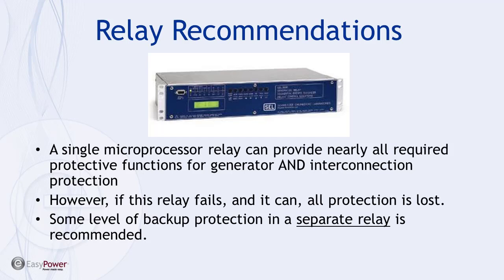However, if this relay should happen to fail, and they definitely can, you go from having wonderful protection to having absolutely no protection. So you're going to want some type of backup in a separate relay. Some people will just duplicate these two relays, have identical relays with identical settings, and that's fine. Or you may go to something a little less elaborate, but you're going to need a separate relay that can provide some backup protection.